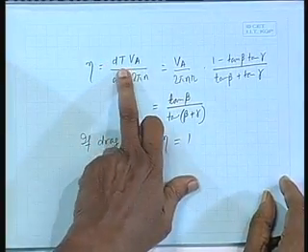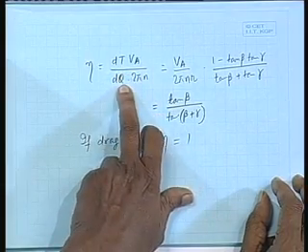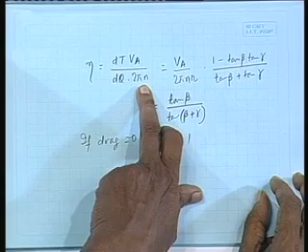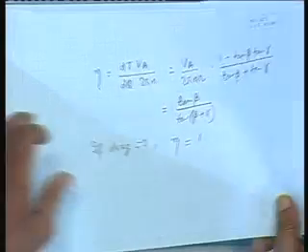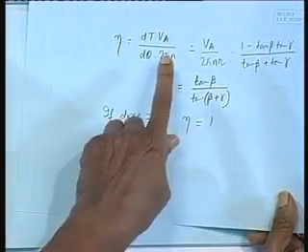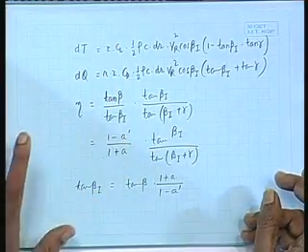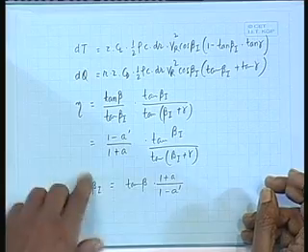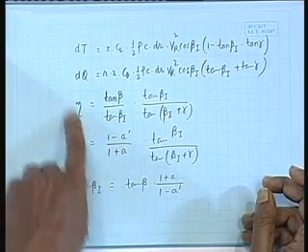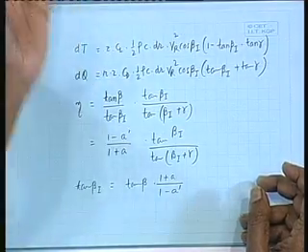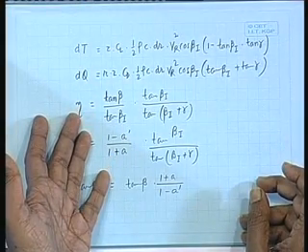D will vanish, we have calculated the total thrust and total torque. So, T into V A divided by 2 pi n Q will be the efficiency of the propeller. You can go ahead and do this, there is no problem there. But suppose we had designed our elements in such a manner that all the elements have this efficiency eta, then I need not go through this, my efficiency of the propeller will be same as this efficiency.